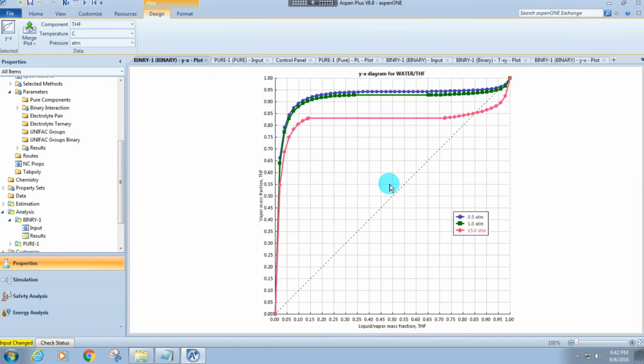Now, with this distillate stream, what are we going to do with this in a pressure swing? We're going to increase its pressure to, let's say, 15 atmospheres, and feed it to a second column to produce a bottoms and a top again, right? Now here, what's interesting is our distillate stream here, I drew this wrong. 1 atmosphere, so it's around there. So 94% was right here. That's our distillate stream coming out from that first column. It is now our feed stream to the second column, right?